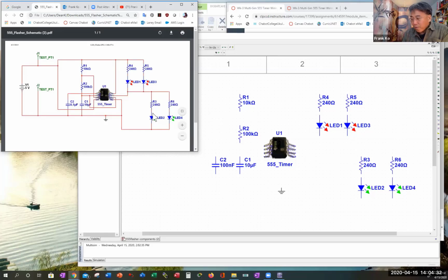So if you remember the very first circuits we built together many weeks ago, your circuits contained LEDs for two reasons. The primary reason for containing the LED was to show you that, yes, the circuit was built properly, because if it lit up, it was in the current path, and it gave you a visual cue that something was hooked up correctly. But in conjunction with the LEDs had to be resistors, and the resistors were there to keep the LEDs from burning out.